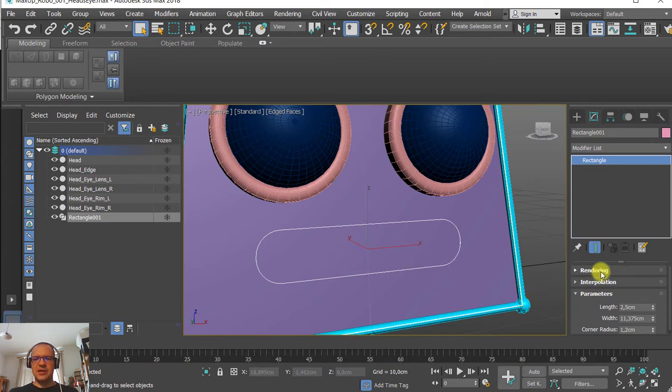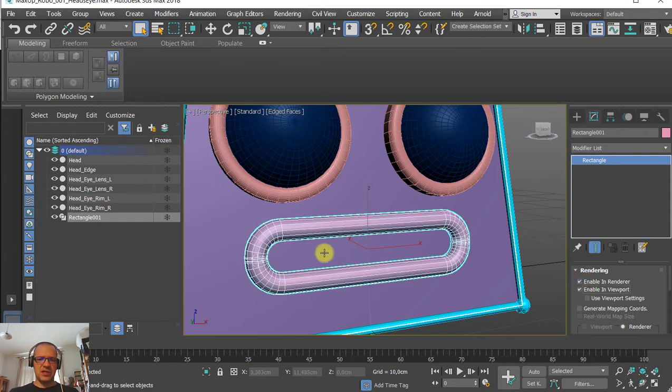So that is depending on the rendering options. How is it rendered? If it's rendered as a wire, this is how it looks. If it's rendered as a 3D mesh, this is how it looks. Now we have two ways. The reason is this solution is often used for rigging. And in rigging, you don't want to see it in the final. These are just helpers when you are rigging and using these shapes as helpers. So we can split this up. If you want to enable it in a renderer and enable it in viewport, this is how it looks.